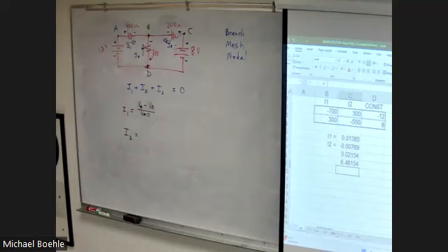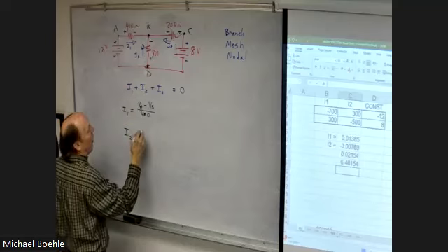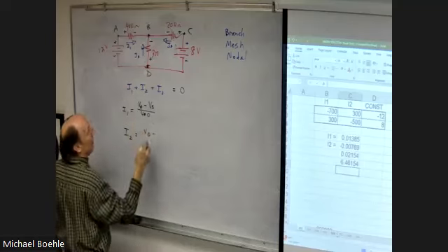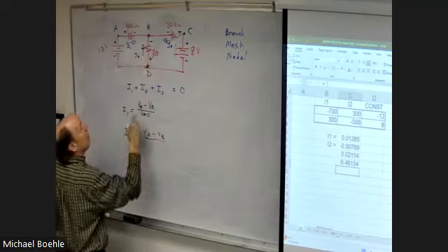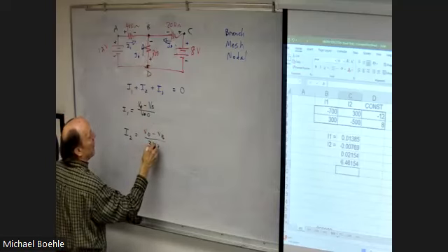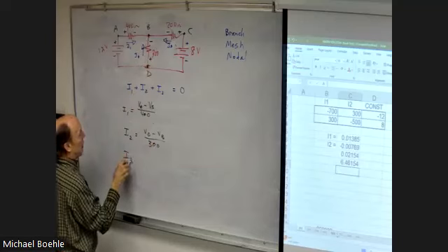So that same technique. Exactly. All right. The polarity tells you which numbers to subtract, right? So the plus is where we start, voltage point D minus voltage point B, and it's a 300 ohm resistor this time. All right, what about current 3?